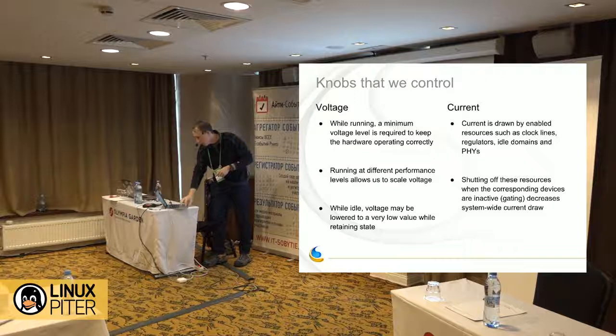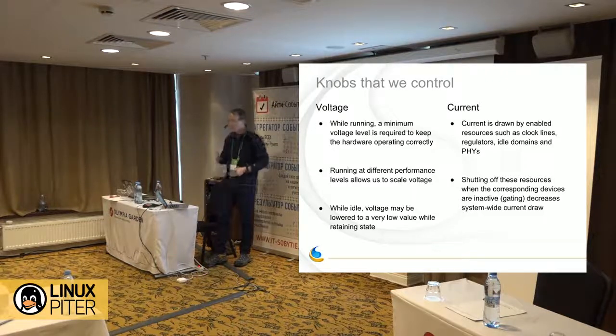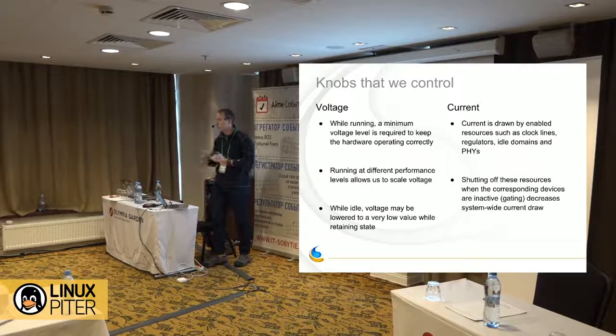On the other hand, current is more of an on or off affair. We tend to think of this as clock gating or power clamping, power islands, which we'll get into shortly. And this is really a binary, on or off thing. These are the two main knobs that we have. We can scale voltage or we can power clamp stuff. And those are the fundamental knobs that we have to play with from software in order to actually save power.